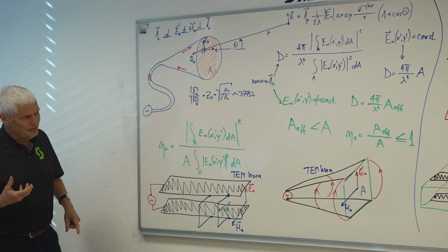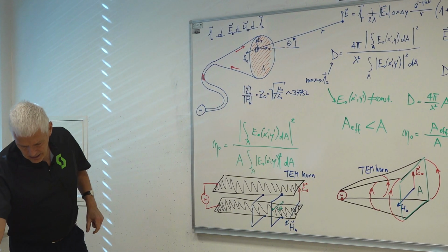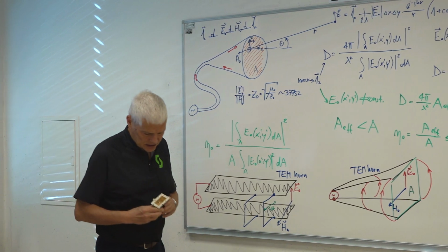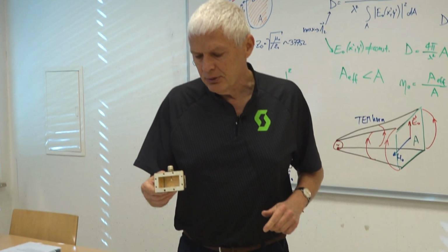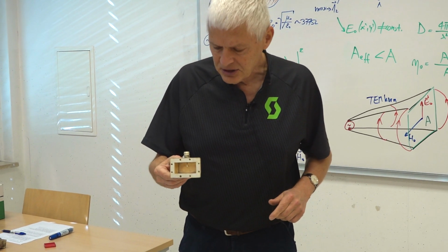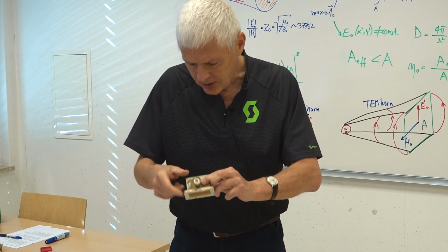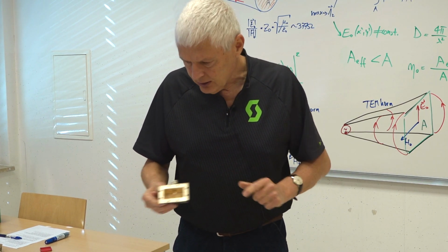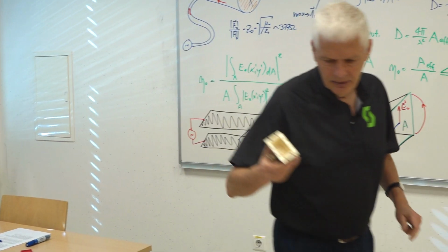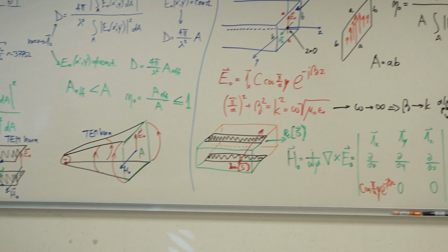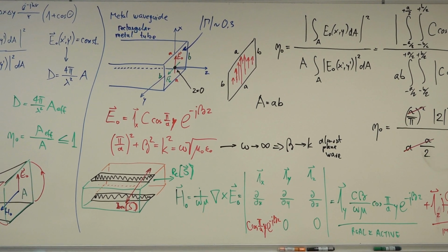And not like here, because here these wires are going to radiate elsewhere. So we have to think about how to illuminate our waveguide without making additional radiation. And this is a transition to a slightly larger waveguide. I intentionally brought this one with me because it's large, so you can see how it is done. This is a coaxial connector, 50 ohm coaxial connector, going to the waveguide. So this one here or this one here is the same piece. It's a larger waveguide for lower frequencies. That's all about it. And how is this thing done?